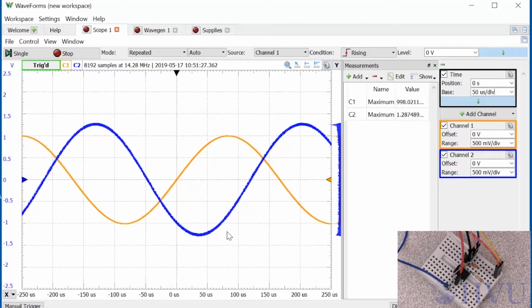It's still about 1 volt. The output amplitude is about 1.3 for this frequency. This is close to the gain of about 1.4 that we'd expect at this frequency. The differences could be due to the fact that I'm not applying a voltage that's exactly at the cutoff frequency, or that the actual capacitance is likely different from the nominal value.